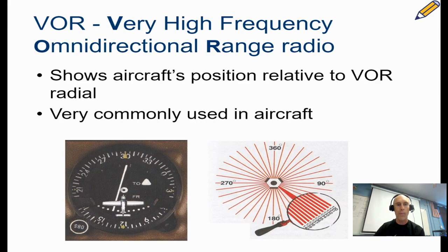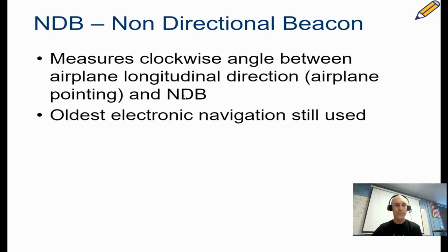And let me go back to this. Go back to your VOR notes right now. I want you to write down that you cannot actually tune to a VOR unless you reach a minimum altitude. It kind of depends on where you're at and where the VOR station is. But your beacon in the airplane may not pick up that frequency on the ground. It may, but it may not. So there are some that have a minimum altitude. So you just want to write there is a potential minimum altitude for VOR usage.